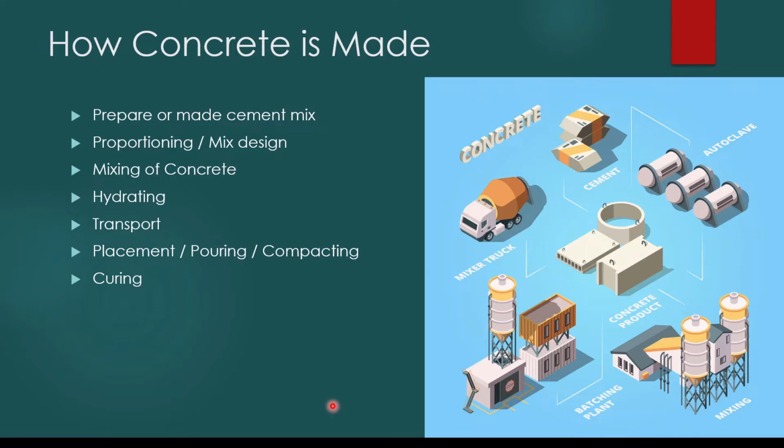Once you have the cement, the next stage is to do the proportioning of the mix. There are two methods for this. First is volume batching and second is weight batching. Depending on the batching or concrete mixing method, we have to proportion the concrete. First we discuss volume batching. In the early days we mostly didn't have the weight batching method, and volume batching was the most common.